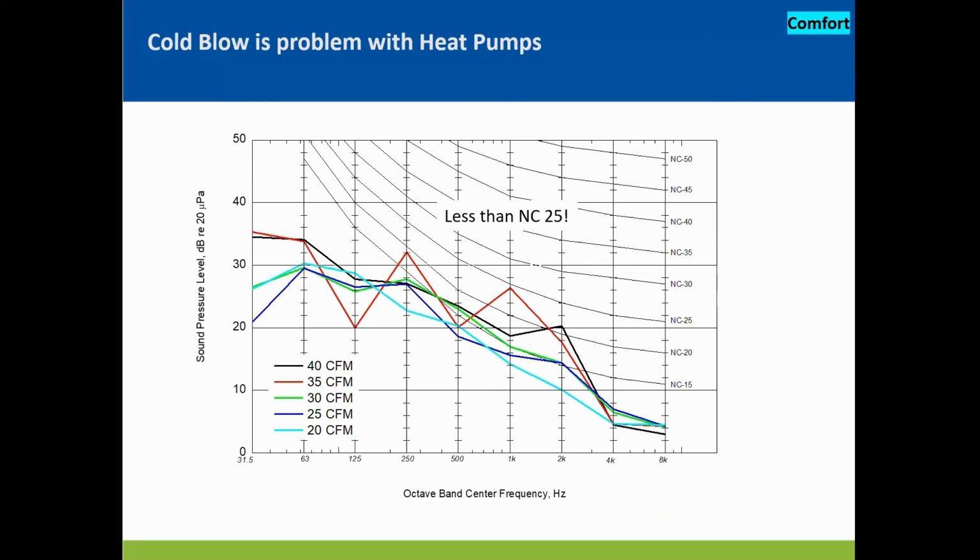In terms of noise, we've measured the sound pressure levels from the registers. All the small duct high velocity manufacturers have a sound attenuator, which is like a muffler, and does a very good job of keeping the noise levels down to a minimum. These are very quiet systems. I've seen them even installed in sound recording studios. So that's not an issue, although some people might think it is because they hear the words high velocity and think noise, and that's just not true.